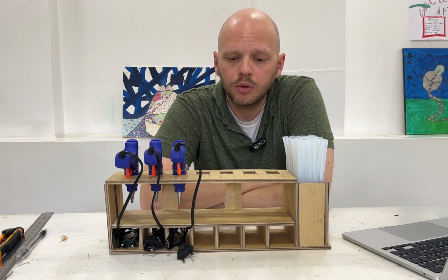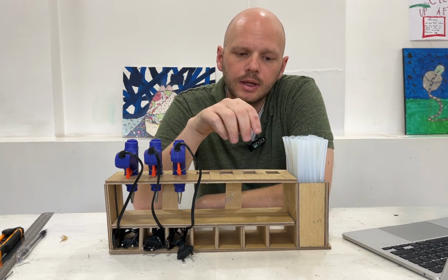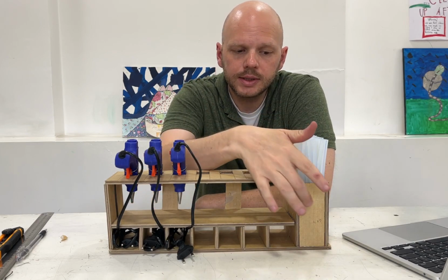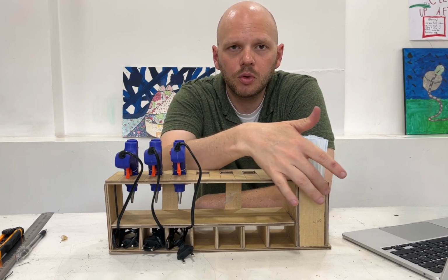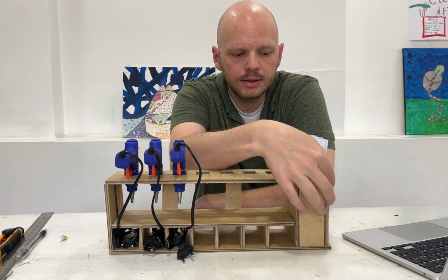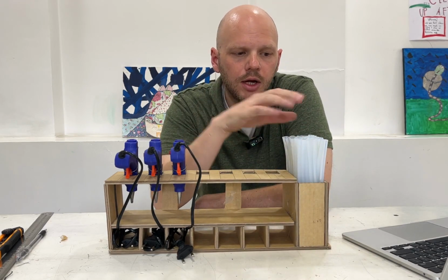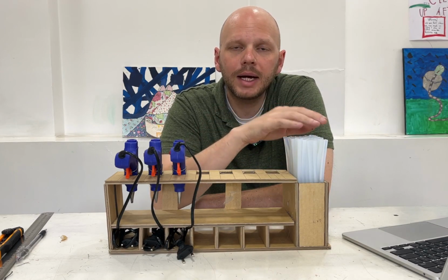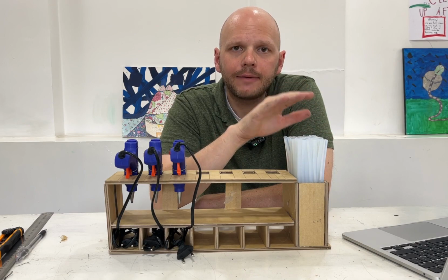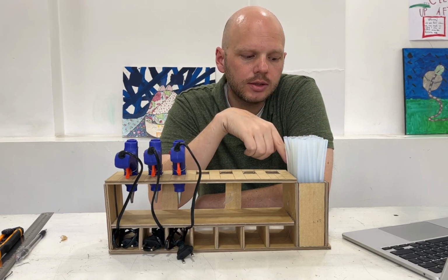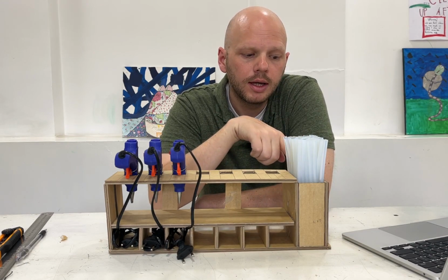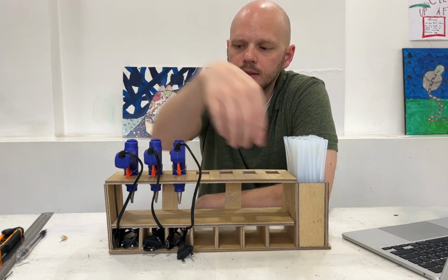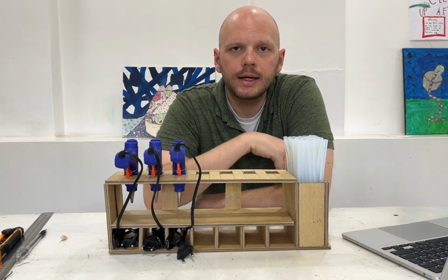First mistake, or first thing I didn't consider, is I'm using pretty thick cardboard, so actually the thickness of the material. So what I had to do is these 6 centimeter wide pieces, I had to cut off the thickness of both sides here, so they're actually narrower. So all of my glue sticks don't fit, so if I was going to edit my design for my final design, I would change it so that I make the whole thing a little bit longer, and that can be a full 6. So I would account for the thickness of this, and this in my design.